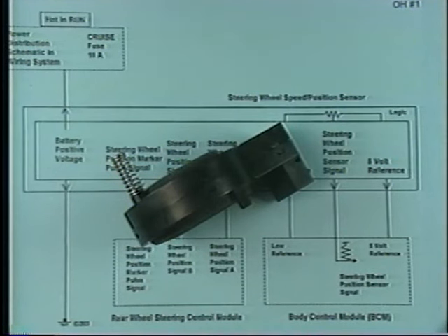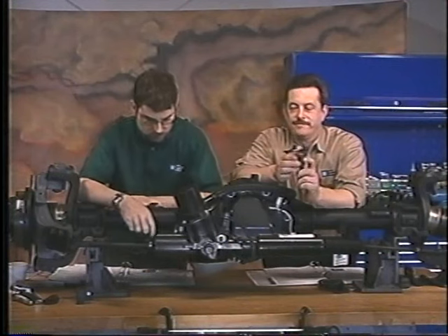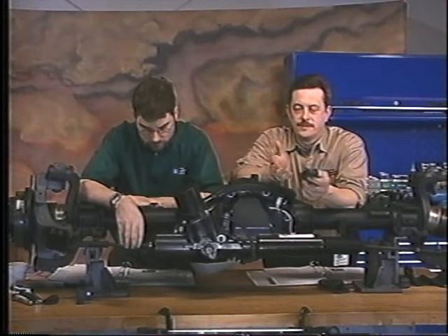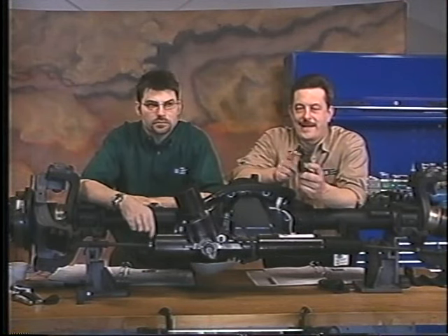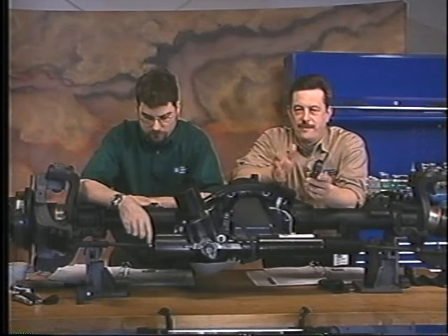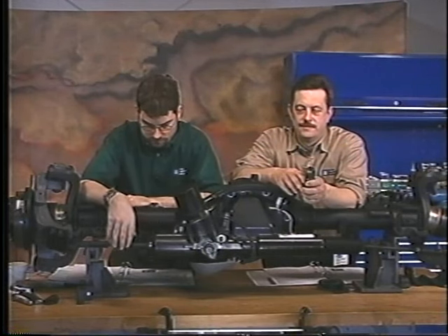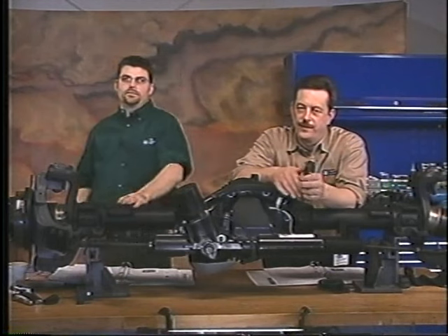All right, and also, we talk about that steering wheel position center. Obviously, there are times where you're going to take a column apart to make some repair to that column. You're not going to have a shift pin, okay? Before you disassemble, make sure you've got the column in the straight ahead position. Go ahead, do your disassembly, make the repair, start putting things back together.